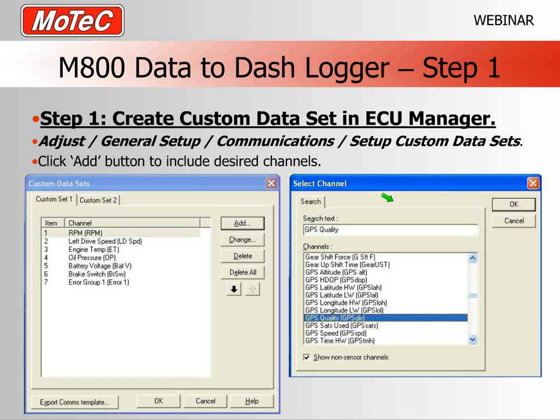Now, this table shows a list of the channels that are available in the M800 or the other 100 series ECU that may be transmitted upon in the custom data set. Now, you'll notice down the bottom here we have checked that little checkbox that says Show Non-Sensor Channels. Now, this is quite important.